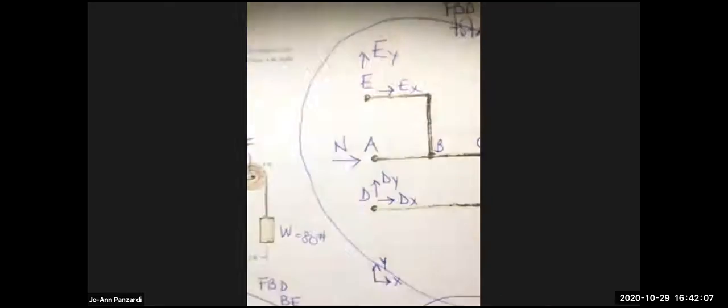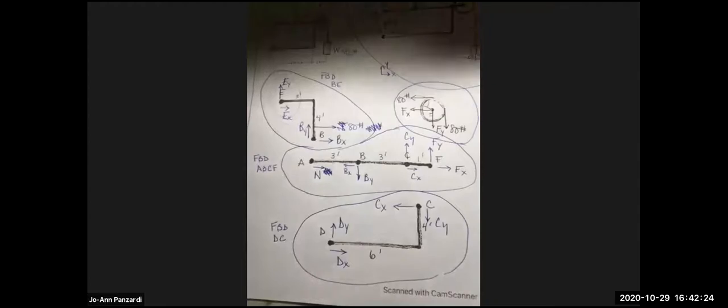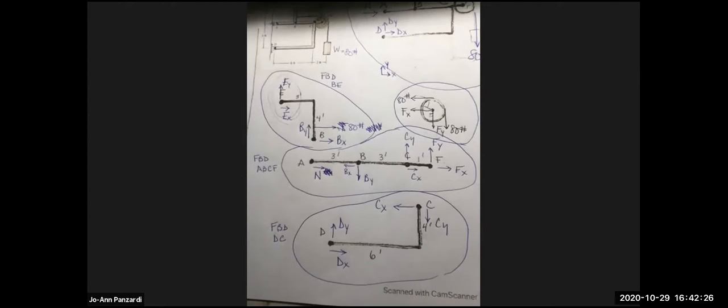So when we drew the free body diagram for CD, let's go back to our free body diagram for CD. Everybody could see it? Notice we had a CX, a CY, a DY, and a DX. But now we know that because it's a two-force member, we know where the directions of those reactions are. So what should I draw instead, Edgar?